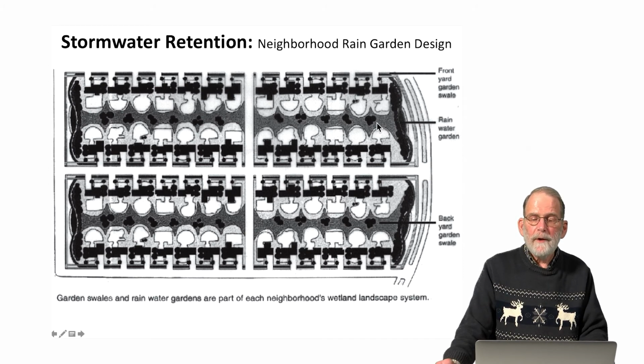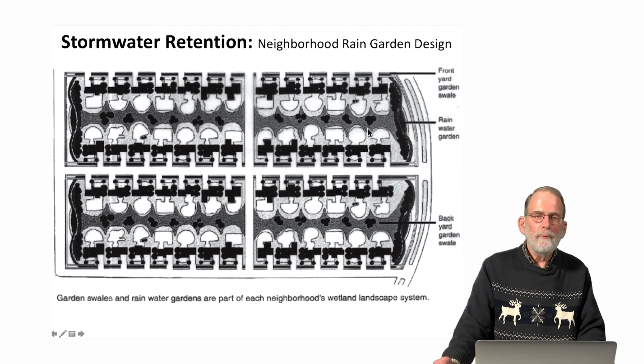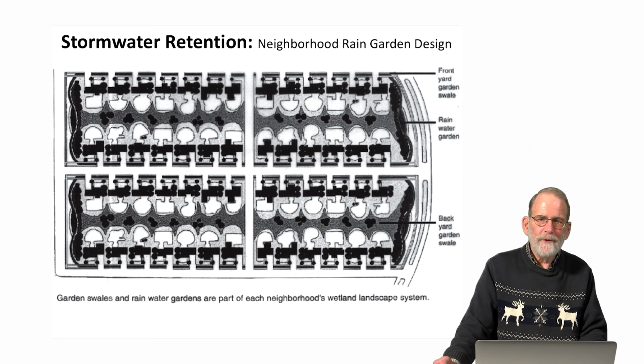And the bioswale then is designed to retain all of the runoff that is generated on site and to infiltrate that runoff. So these residential neighborhoods that typically might have had a runoff coefficient in the neighborhood of 0.45 to 0.65 are going to be down around 0.1 to 0.25 in terms of their runoff coefficients. That is a reduction from 65% of the precipitation joining runoff to 10% or 15%.